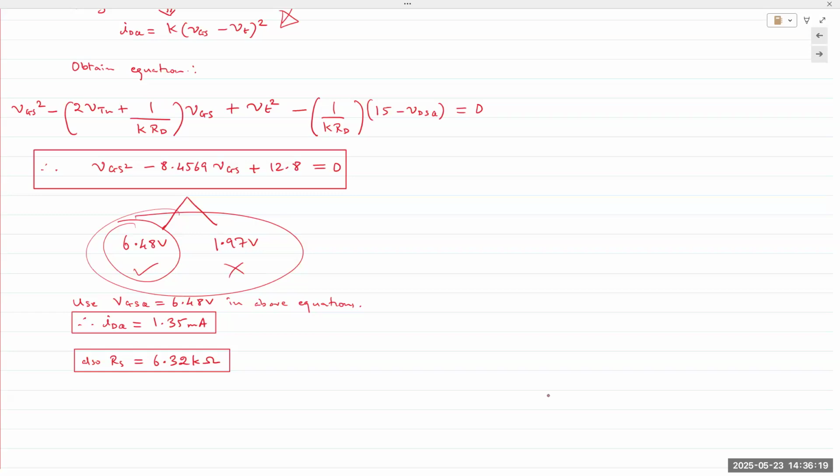Threshold voltage is 4 volts. Anything we apply in excess is gate overdrive. So gate overdrive voltage could be 1 volt, 2 volts, 3 volts. The system will still work. So the system would work for 6.48 volts. If this 1.97 was 9 volts or like 5 volts, it could possibly still work. So it just depends on what values work best for our application.